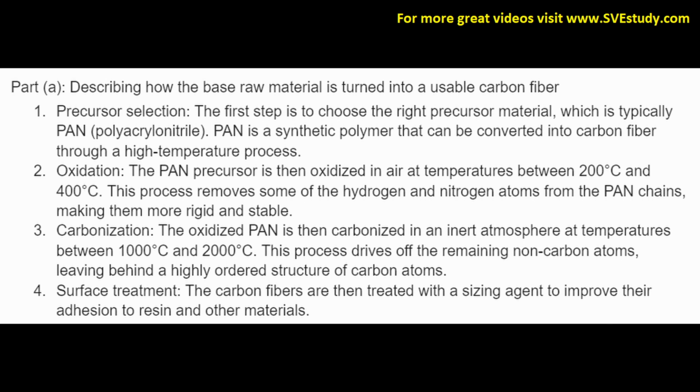2. Oxidation. The PAN precursor is then oxidized in air at temperatures between 200 and 400 Celsius. This process removes some of the hydrogen and nitrogen atoms from the PAN chains, making them more rigid and stable.